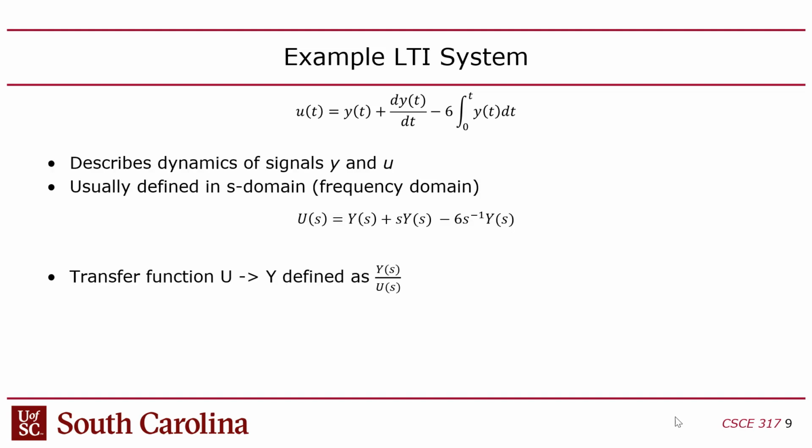So when you do that, the way generally that that's done, there's actually two ways to do that. You can do it with a state space equation or with a Laplace equation. So I'm going to first cover the Laplace way to do this. If you take the ordinary differential equation and you take the Laplace transform, basically you're going from time domain to frequency domain, so t domain to s domain.